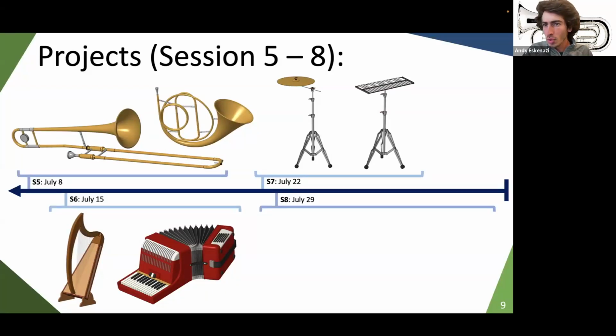Finally, just recently in session 7, we started to learn how to use assemblies, because all of these instruments really are in reality assemblies of different parts. But sometimes it's easier to CAD as a single object, a single part, as opposed to all different ones. And we've really exploited to the maximum this technique of the master sketch, where you have a single sketch and you're kind of referencing every subsequent part that you'll be doing with regards to the master sketch. And that was why really CADing the overall general frame was not very difficult.